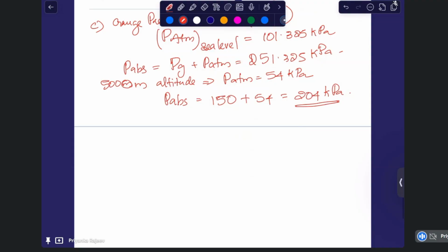Whether it is at 5000 meter altitude or at sea level, we are using almost similar stove and everything. So heat input will be a constant value and pressure has varied. So temperature requirement is higher at high altitude. That means we have to prolong the process of giving heat so that the system reaches that temperature. So that means cooking time has increased. Okay, cooking time increases.